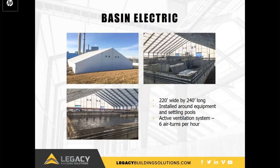This bottom ash dewatering facility in North Dakota measures 220 feet wide by 240 feet long and uses a hot-dipped galvanized steel frame. The combination of steel and fabric allows for the wide clear span area, which was specified to accommodate the equipment and settling pools, most of which were in place during the building's installation. The ventilation system in this building, including exhaust fans and ridge vents, is designed to produce 6 air changes per hour.